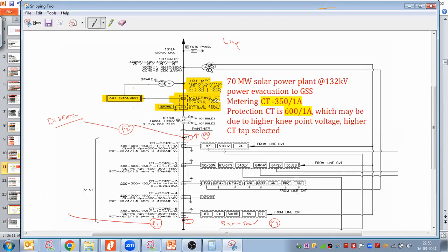You can see the star point here. Here, this is my sphere. Okay, you asked about shorted and grounded. This is my line protection, so I took this for the line. Grounded. This is my metering, so I took this middle point. But I do not need to take the middle point, take the S1 point, this one. Here, no problem, anywhere we can take. But this is my line protection, overcurrent backup. So S2 here, right?